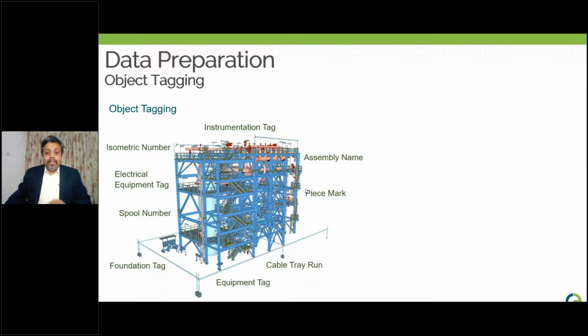When I deal with new project data, I can say that we are much better now than we were a couple of years ago. Piping, equipment, and steel disciplines show a big improvement in tagging construction objects. And these tags are used as a unique identifier in the project to reference them. It is always good to create tags when we create the data. More important is to create meaningful tags. If it is an intelligent tag, the automation will be much easier, smoother, and more accurate.